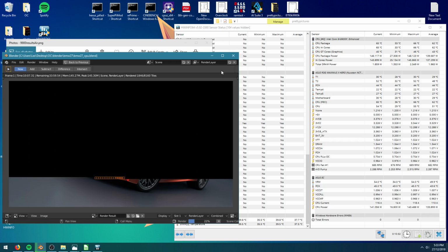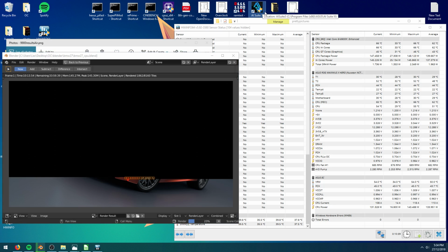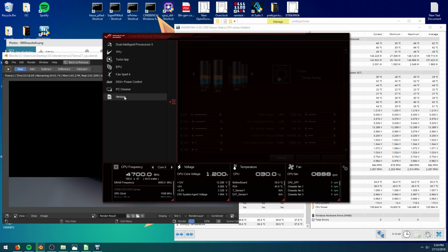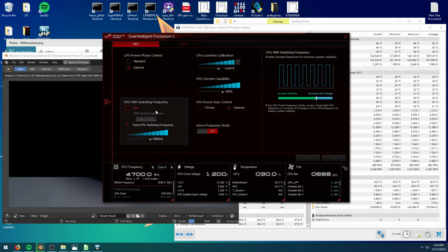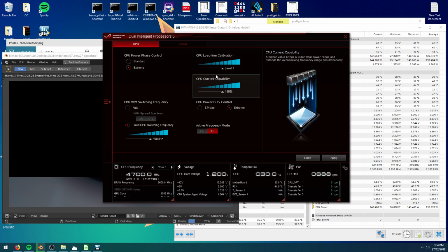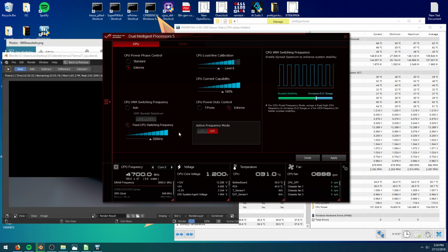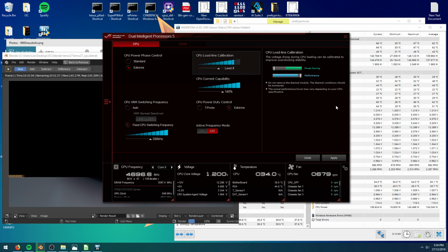So yeah, pretty much that's everything you would probably need to know. One thing to consider, if you're unaware, is a very important thing that not too many people talk about: load line calibration. It's very useful to have an application that you can change your settings live, but it can cause your system to crash randomly if you do hit apply. But your LLC is load line calibration, and it's how much compensation your voltage gets.